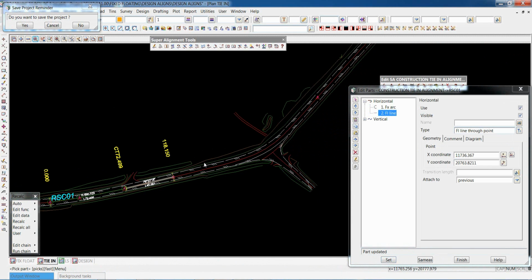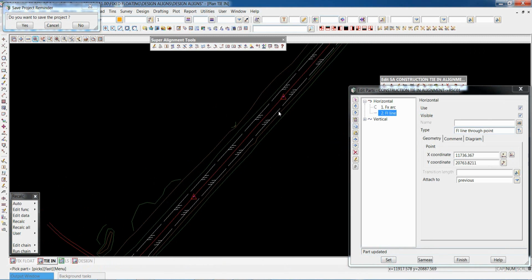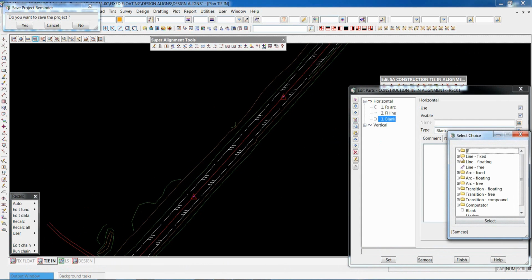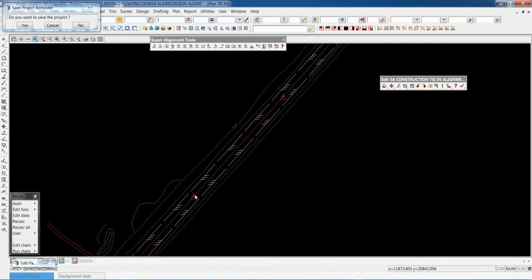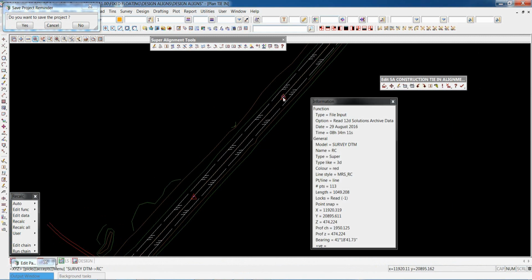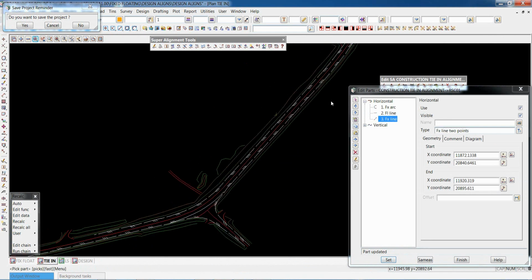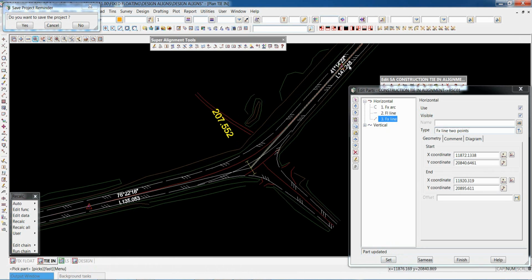I want to put a free arc in here for the deviation, but I'm going to go back onto my 2 points along my straight, and again insert another fixed line. So I picked the 2 points up, picked that point, and the second point. So again, it solves because it now finds the intersection of the solved floating line here and the 2 fixed